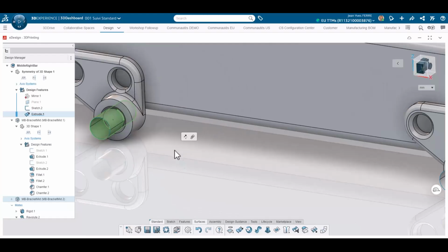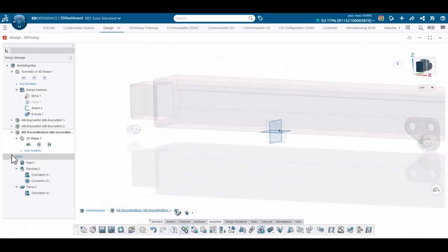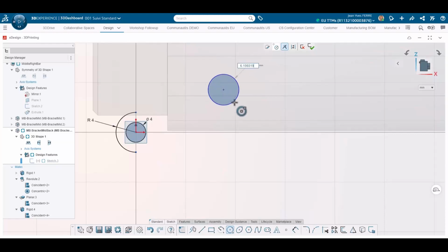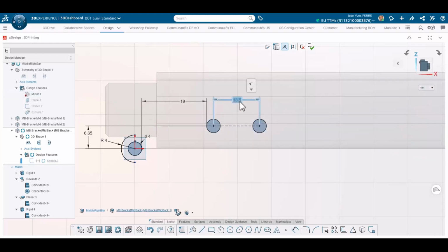There's only one last mounting post to create, and I will use the same technique as before. I represent holes in a sketch, and I add some material around them. I make sure these holes are aligned with other ones with dimensions and relations, and I create the outer shape. As before, I create lines and tangent arcs without changing tools. This is very convenient,